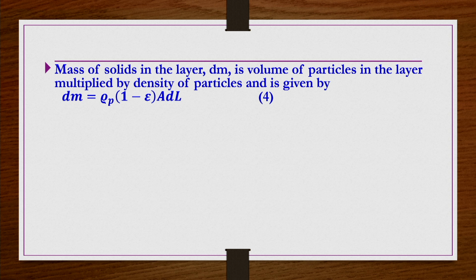So, now as we know, as time progresses more and more particles are depositing on the filter medium. So the mass of solids in the layer is also going to change with time, right. How much mass is being deposited, or what is the mass of solid in that layer of cake of thickness dl that we have taken? That we should calculate, let us say dm.